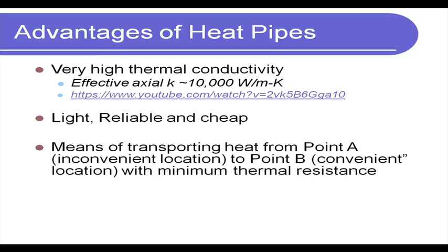Okay. The other advantages of heat pipe, as you can see, are that it's light, it's reliable, it's cheap, and more importantly it's passive. We were comparing it with a pumped loop, and as you can see here we don't have a pump. The wick performs that function, so there are no mechanical moving parts, so it's very reliable. Once it is made and it is sealed, it performs very reliably and goes on functioning for many years.